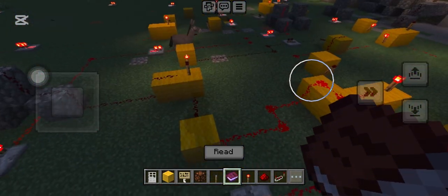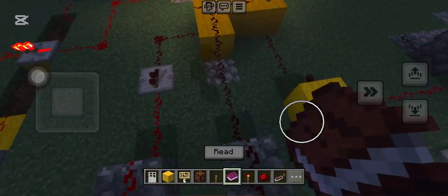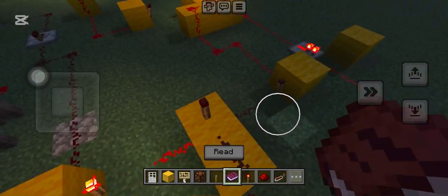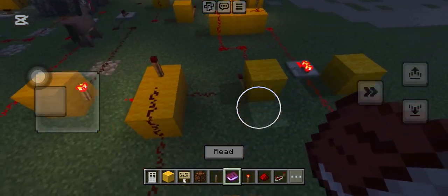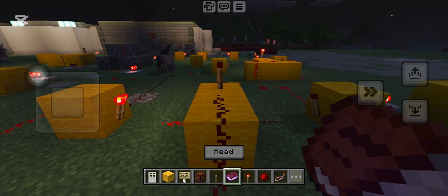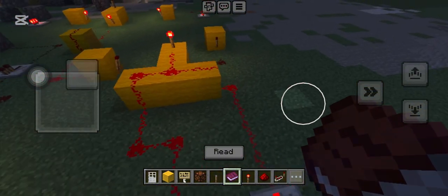Next let's go to round 2 for bit 2. It combines the partial sum with the bit 1 carry. So here is the carry from bit 1. You can see we connect it to the partial sum to make an AND gate, to check if both the partial sum and the bit 1 carry are on. Its output is called the second partial carry. This is mostly used for a 4-bit version or something, but for us we only do 2 bits, so I think it's not necessary.